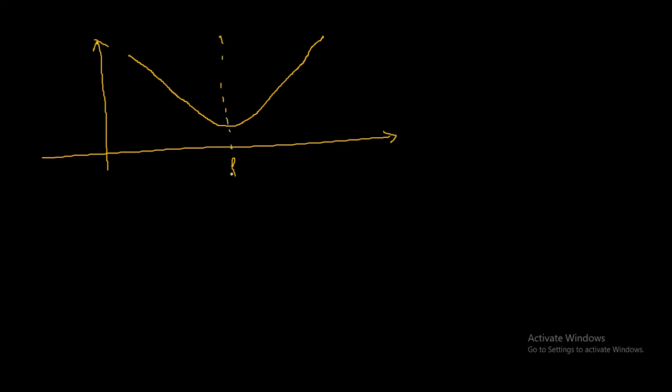So a practical capacitor doesn't show capacitance for all frequencies. If you look at this behavior, this is the resonance frequency. This is the capacitive component, and this is the inductive component.